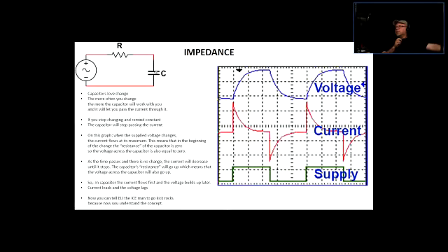And because of that, the voltage across the capacitor is going to be, here's the voltage across the capacitor, pretty much nothing, because if it's a short circuit, what's the voltage across a short circuit? 0, all right? Sorry, I apologize for using the word nothing. I always give you a hard time for saying the word nothing, and I just used it.